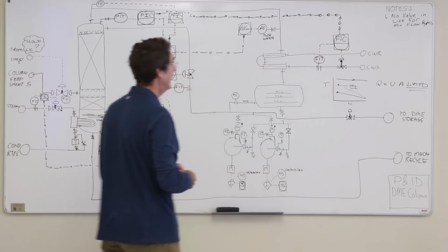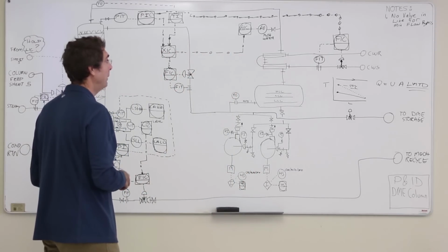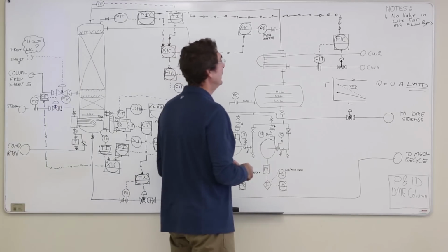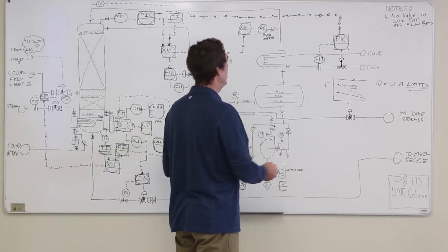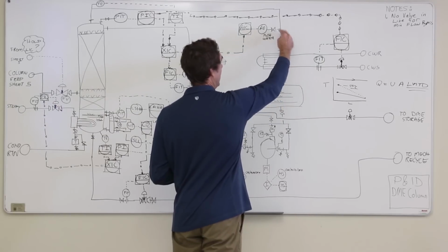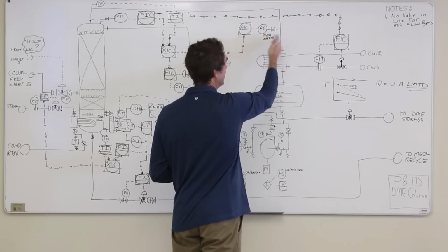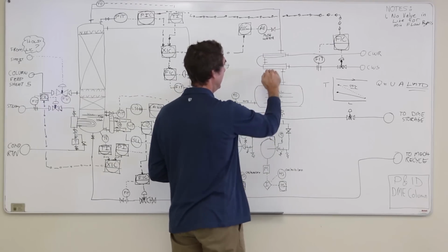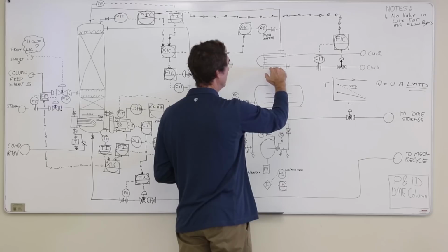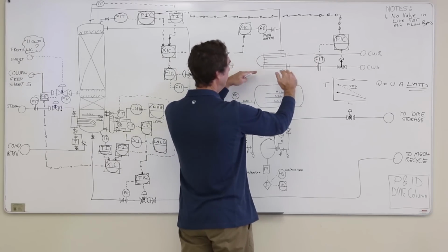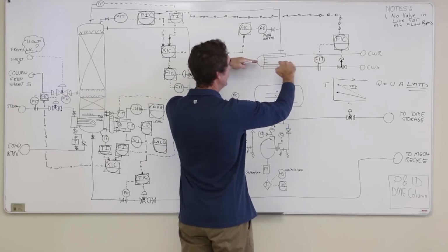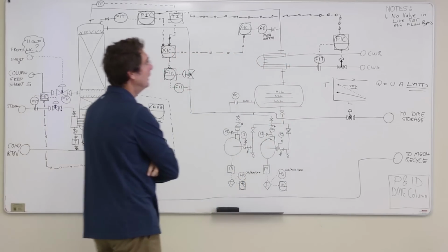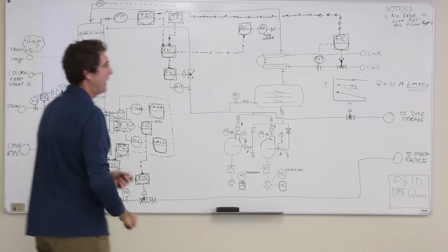So that's one way to do it, but you lose the pressure control with that. So in order to do the pressure control, you need to either put a valve in here to throttle, hold the pressure back in the tower, or let it come down. Another way to do it, if it's a shell and tube, is you can actually flood the condenser on the process side and reduce surface area. I'll maybe talk about that a little bit more on Monday.